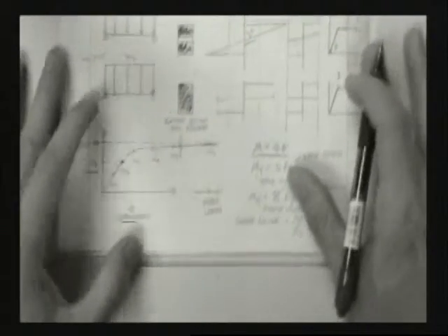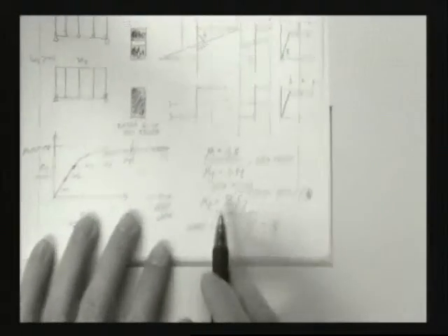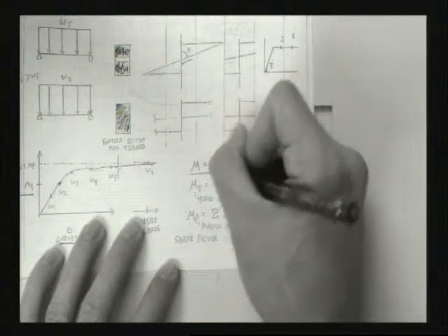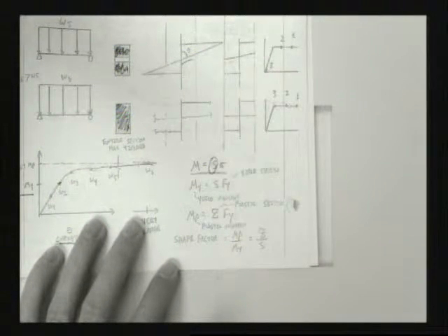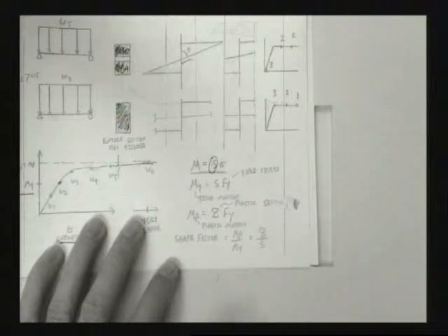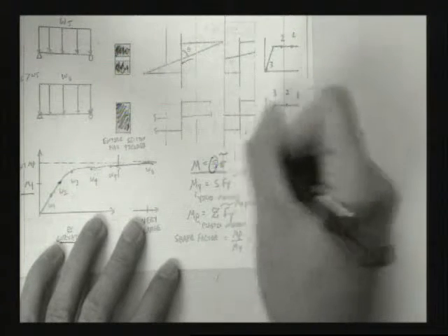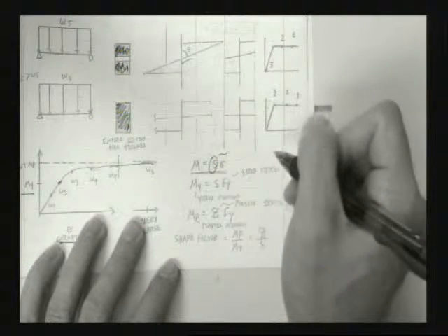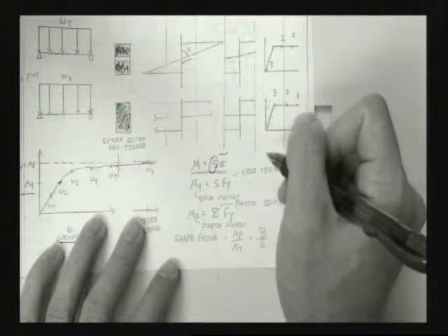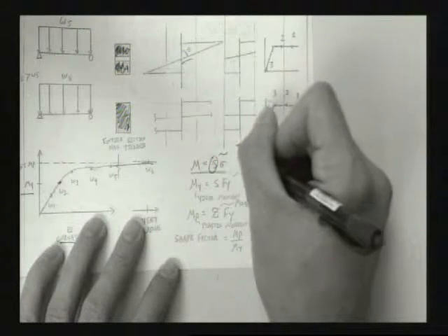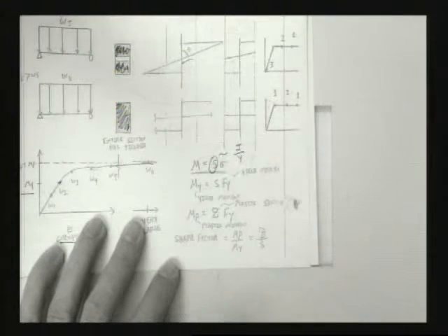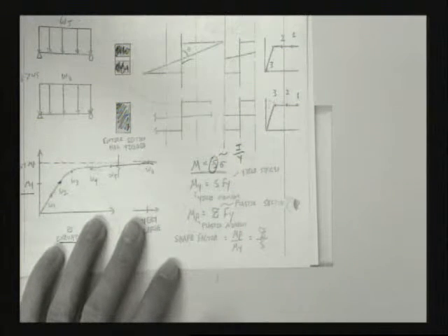Okay, awesome. So we talked about this before. There's a couple things you've seen before. Remember talking about the S? What's the equation for S? What's it called? Section modulus? What's the equation for it? Do you remember? No. I over Y. Thank you. And remember, it's the I over Y that creates the largest or smallest S.